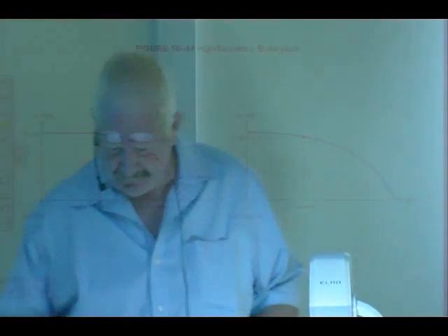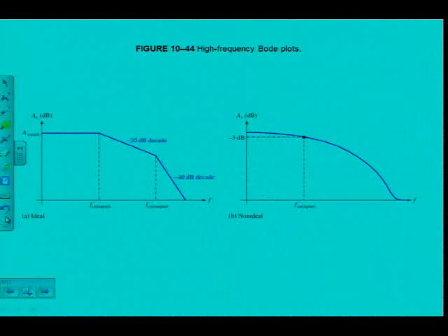there I can see my two RC circuits formed by the transistor's internal capacitances. There's my mid-range. Remember, the amplifier will amplify that fine. As soon as the frequency becomes too high, then this happens. Minus 20 dB for the one and another minus 20 dB for the other one.